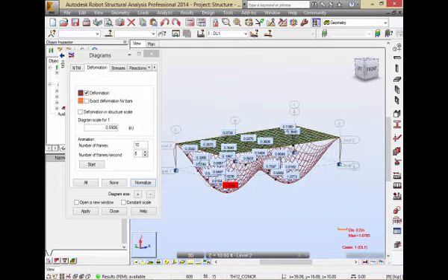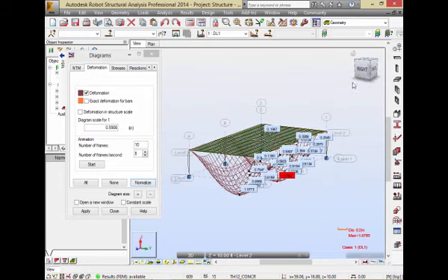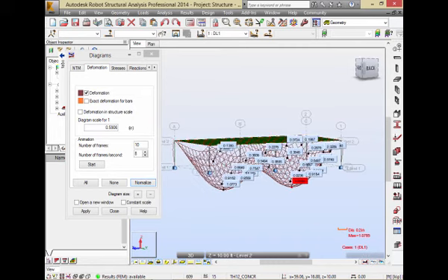Right now it's dipping in two big areas. That's because these giant 30 by 30 foot bays just have beams around the outside. I really need to go back and put some intermediate beams to shore up that floor. With the type of floor I have right now, there are huge deformations, and you can't go ahead and have those. That's telling me I need to put some more beams in here to make it all work.